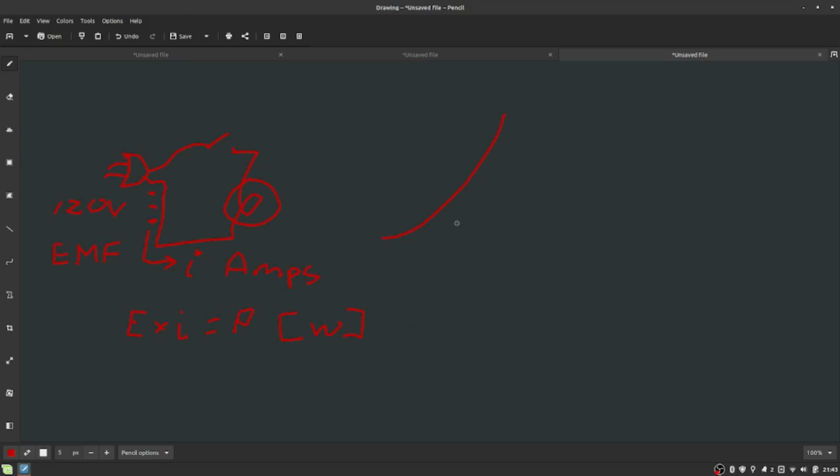So what becomes a lot easier to deal with is, okay, well, every time this power becomes a factor of 10 bigger than itself, so let's say over here it was 1 and over here it's 10, and then if you continue this somewhere it becomes 100. Let's just look at these numbers, and we'll call this 1. We'll do this again. Oh, my screen appears to have died for a second here. So this would be a 1, this would be a 2, this would be a 3, etc. 1,000 would be 4. You'd have something like this. Well, that is the decibel scale. There we go. Now it works. So you have this power in watts, or you can have power in decibels, and you can kind of convert between the two.